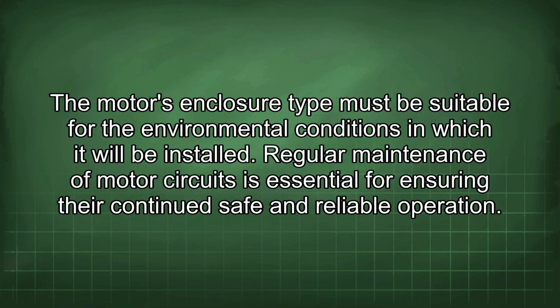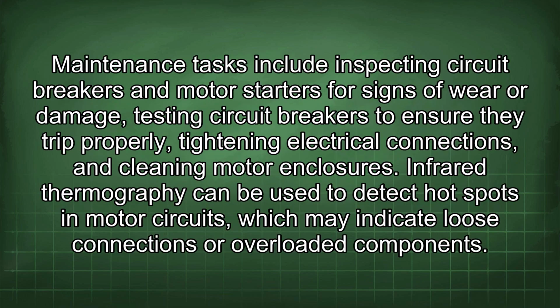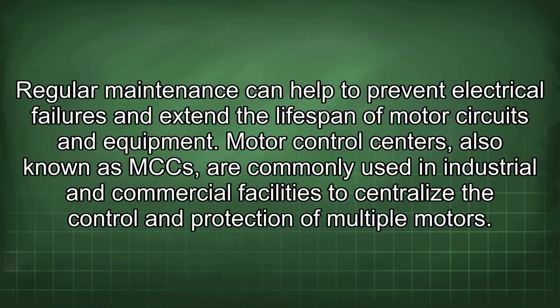Regular maintenance of motor circuits is essential for ensuring their continued safe and reliable operation. Maintenance tasks include inspecting circuit breakers and motor starters for signs of wear or damage, testing circuit breakers to ensure they trip properly, tightening electrical connections, and cleaning motor enclosures. Infrared thermography can be used to detect hot spots in motor circuits, which may indicate loose connections or overloaded components. Regular maintenance can help to prevent electrical failures and extend the lifespan of motor circuits and equipment.